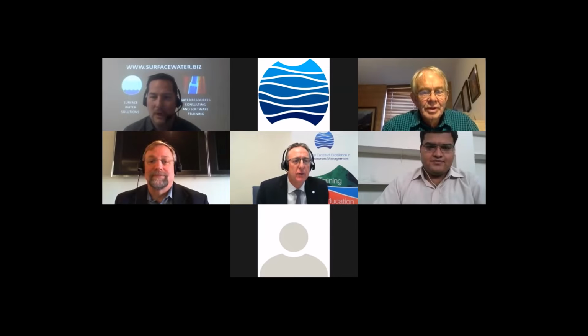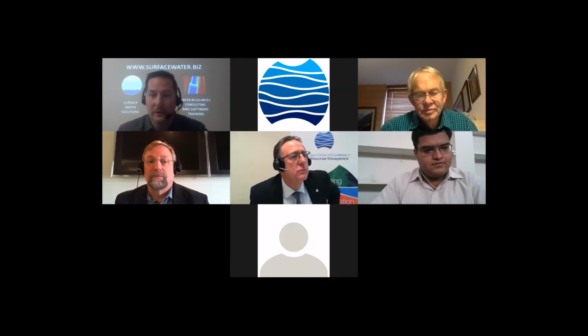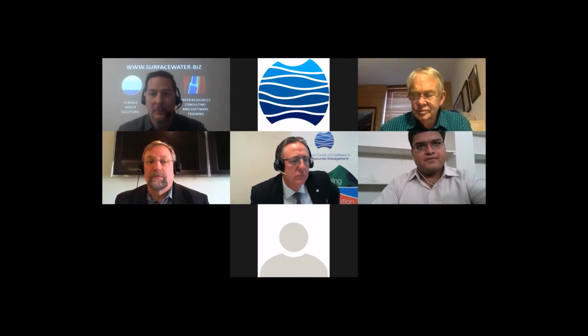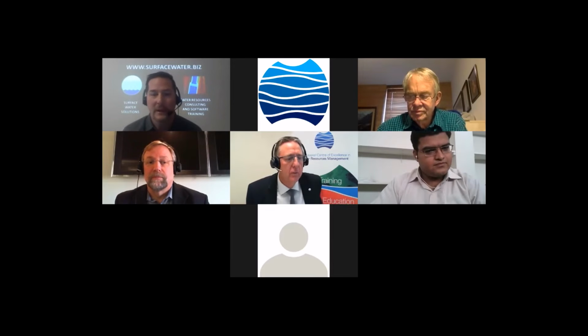I'll talk about just briefly about sediment transport routines. Let's keep them short though, because we're going to need to move on. You can run sediment transport in HEC-RAS, but it's only going to be in the 1D interface. It's going to be much easier to do in steady or quasi unsteady flow. Trying to run a full unsteady flow sediment transport model is very complex. So it can be done. You can simulate these things, but without calibration data, if you don't have data to calibrate to, your sediment transport model is not going to be worth anything.